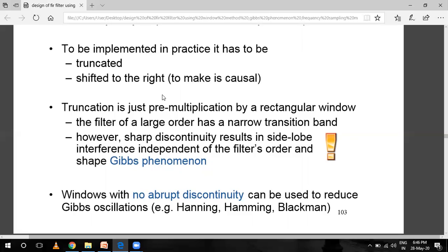Basically, the Gibbs phenomenon demonstration is also available in MATLAB. It is used to convert a sine wave into a square wave by adding a number of harmonics to the sine wave using the Fourier series. With a higher number of harmonics, the output graph shows how the sine gradually converts into the square wave. And when we talk about the effect of the Gibbs phenomenon, the signal being measured has an important role in determining if the Gibbs effect occurs.